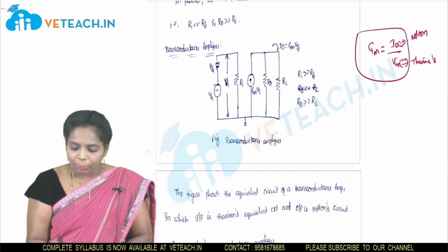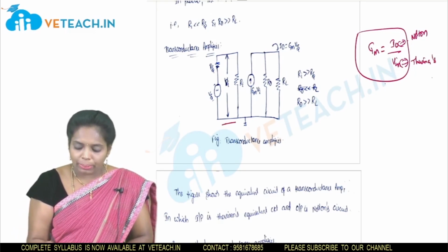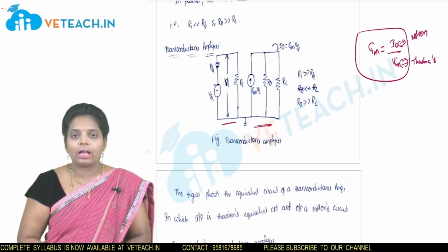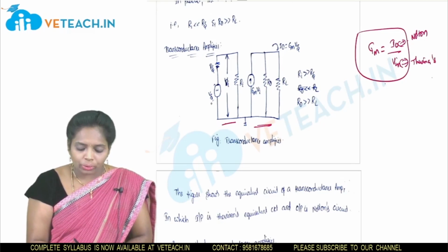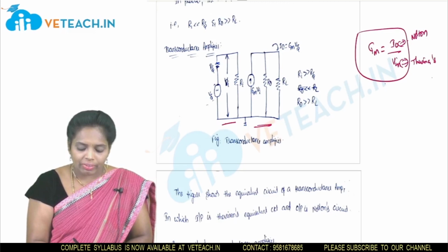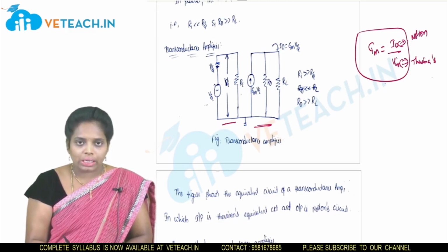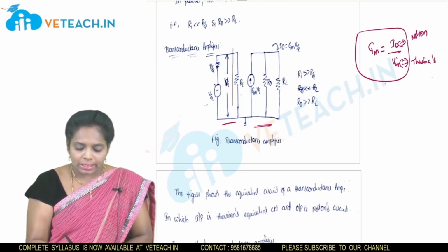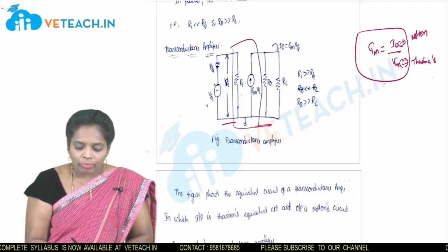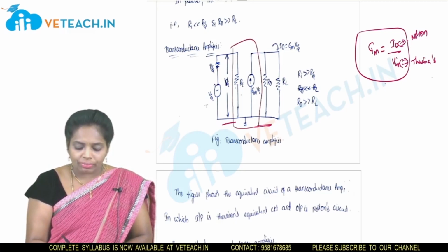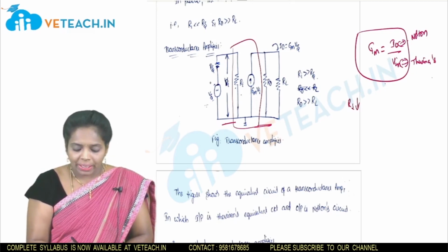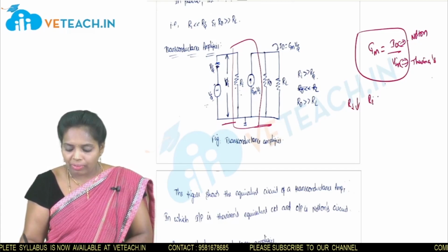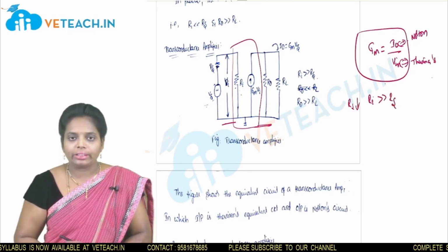Here the input circuit is replaced by the Thevenin equivalent model, whereas the output circuit is replaced by the Norton equivalent model. Whatever external source voltage is given must appear across the input of the transistor. So the source voltage Vs is equal to Vi, which means the value of Rs should be smaller; the value of Ri must be far greater than Rs.